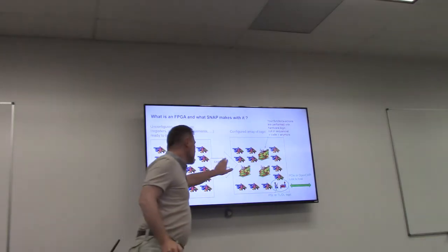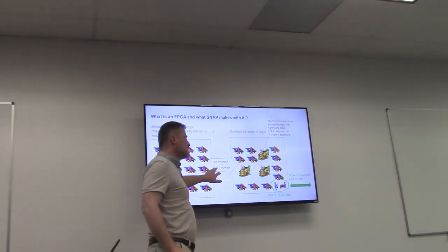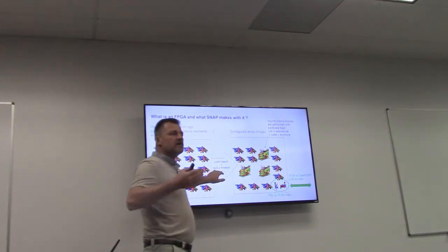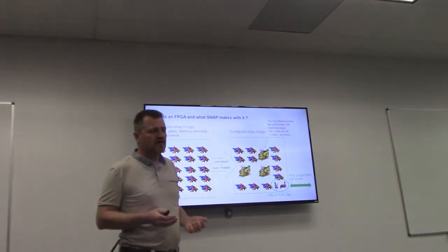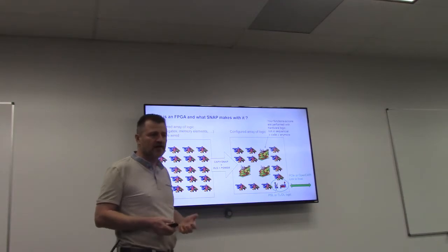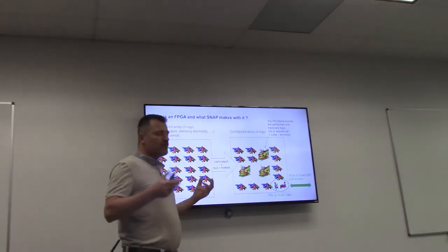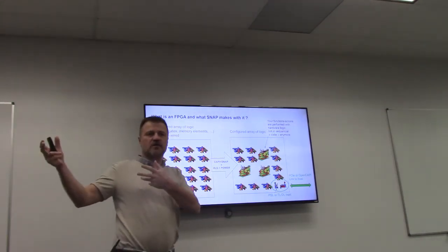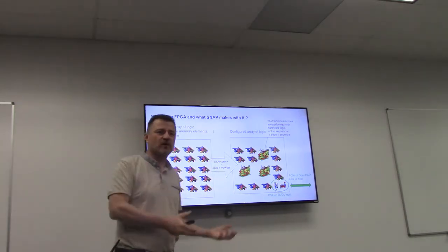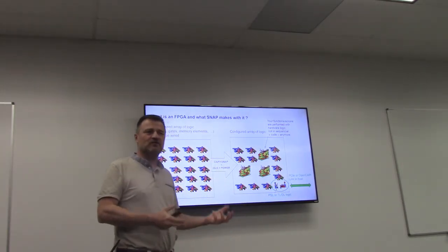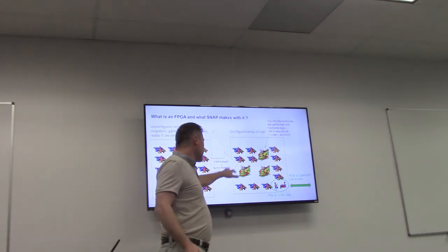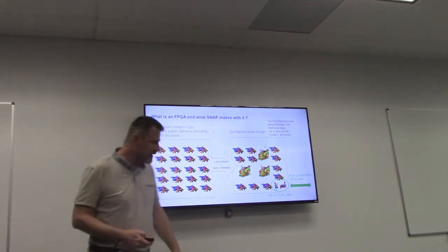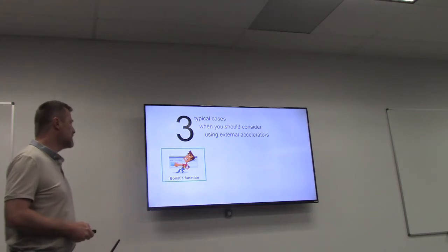And using CAPI with our SNAP framework plus the HLS, which is the nice tool that several companies have built, and we are using the one from Xilinx, but there are several of them, taking some C description of your function and able to describe a logic to put in the FPGA. And all these four things make a very nice application that I intend to demo.